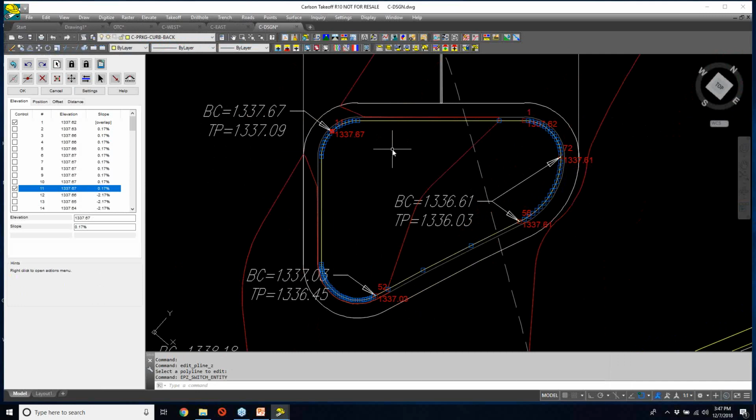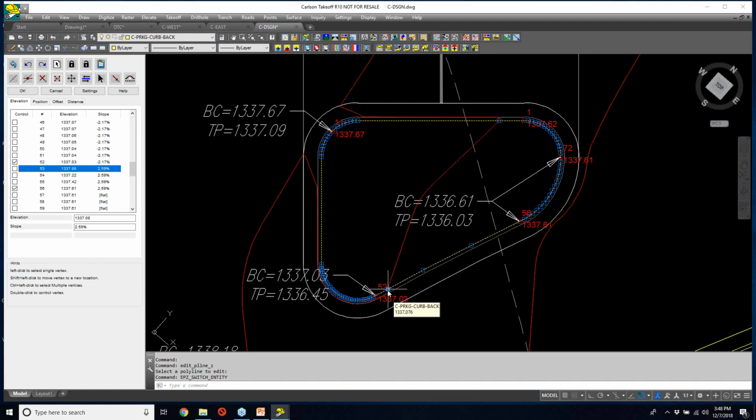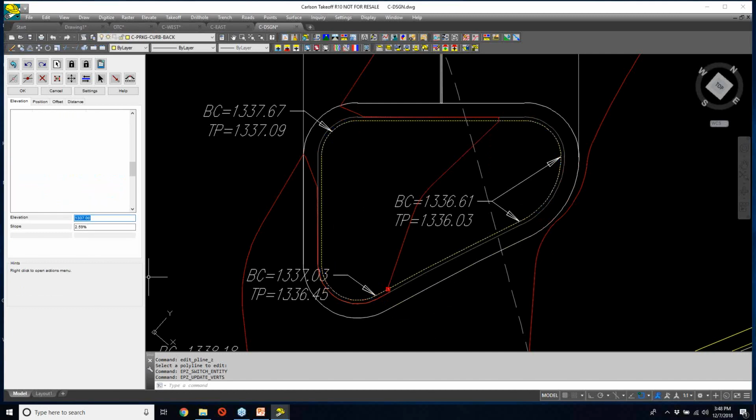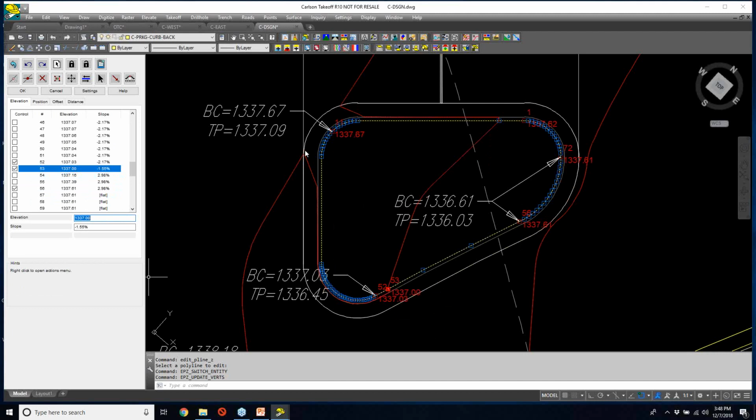And as a result, I have the ability to establish, okay, so like this, I think there was an example yesterday in our presentation. So 52 was linearly interpolated from there up to the next one, and that generates actually a little bit of an error here, because that should be, in this case, probably 1337. So let's just go ahead and manually fix that, get rid of that little anomaly. So we'll manually correct that problem. And probably the same thing here at this spot right there, whatever that guy needs to be. So let's make that also 1337. I think that's the contour elevation.